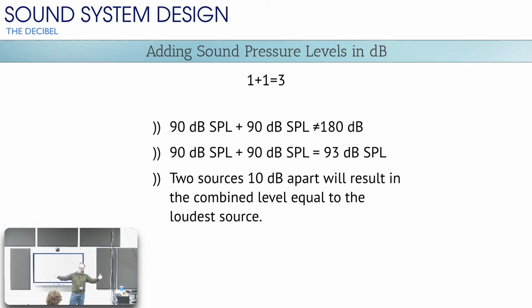Still not there. So now I got to buy 8 more. So now I'm at 16 loudspeakers, and now I've created 12 dB more sound. And by the way, all those loudspeakers are exactly the same, and they're pointed at the exact same spot. That is not a very efficient way to get 12 dB more sound. No, that is not. Okay? So it's much better to get a more sensitive loudspeaker. Get a loudspeaker that's capable of generating more sound per watt of power. Okay? That's what you really want to do.